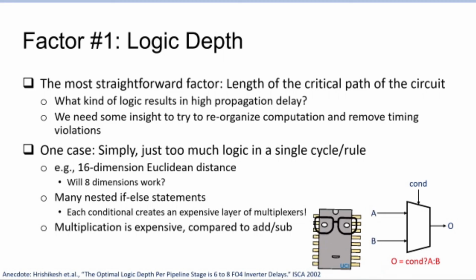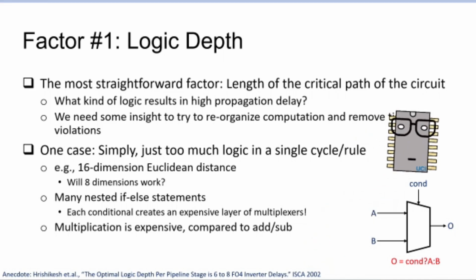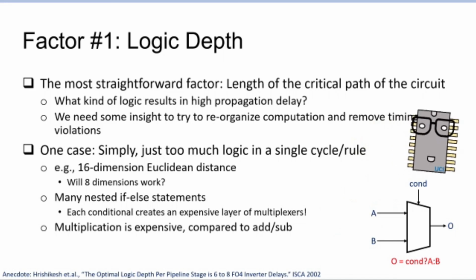Oh yeah, if you have nested if statements, those are typically synthesized into, they actually manifest in the form of multiplexers, and multiplexers are kind of expensive in terms of logic depth. So there's that as well.